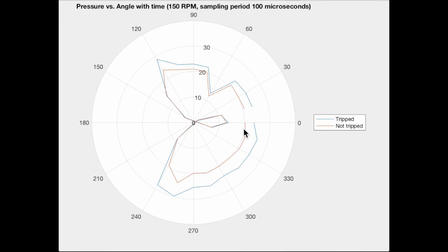We also found that around 240 degrees, which corresponded to port 6, was reading unrealistic data, so we assumed that the port was broken. To account for the faulty port's error, we averaged the adjacent ports' pressure.